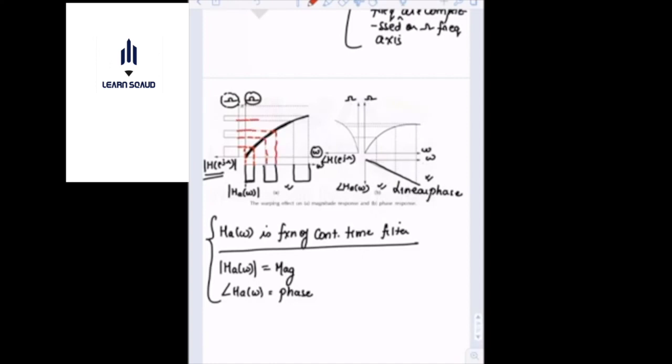Now if we say that the width of these frequencies on the continuous frequency axis is the same, the width on the discrete frequency axis will keep decreasing as the value of continuous frequency omega increases. So we can see that the width decreases. Now this is because of the frequency warping. Okay, very simple to understand.